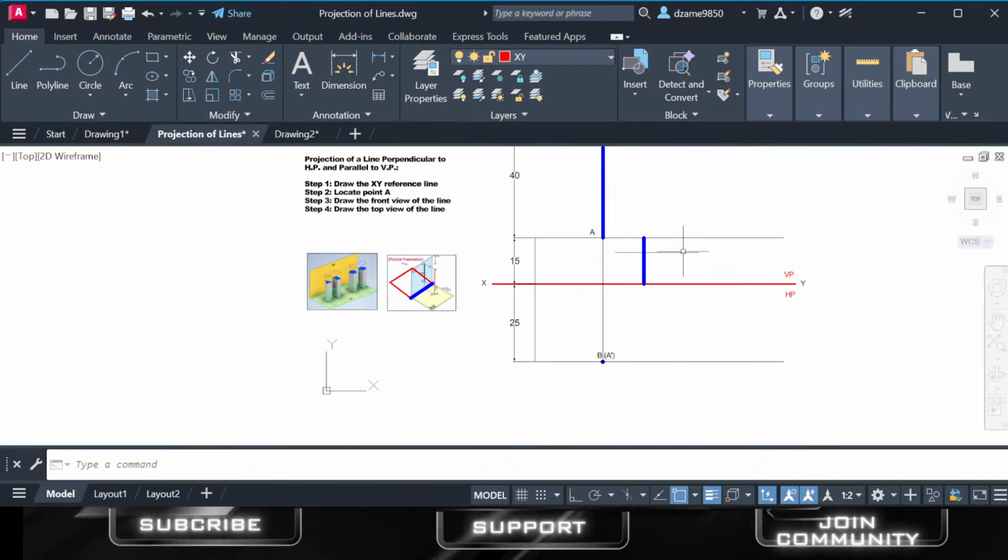In our drawing, I was just illustrating how to measure a vertical line in AutoCAD. It's very simple. In the same manner, I just want to show you. You want to draw a horizontal line of, say, 50 millimeters. Just click the line, click where you want to start, make sure you lock the auto mode, and draw a horizontal line.